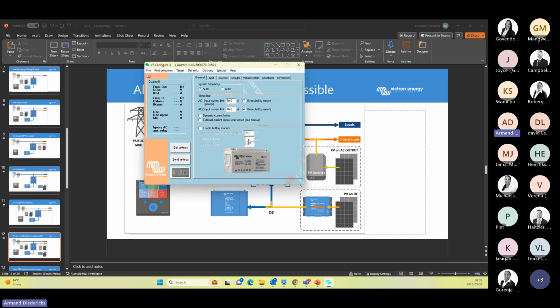With the RS modules, the RS multis, you won't have an MK3. It's not CAN protocol, it's a VE.Direct protocol. So it's a cable, a USB module that communicates via USB to VE.Direct, and that links in, and you'll program the unit via either Victron Configurator, or you'll program it via Victron Connect.